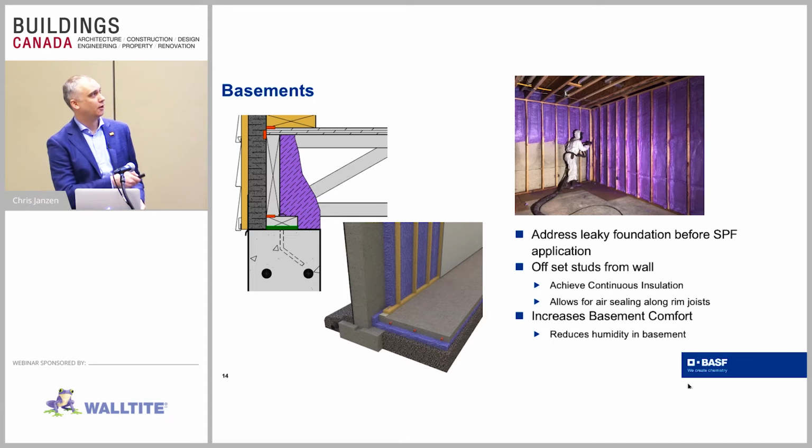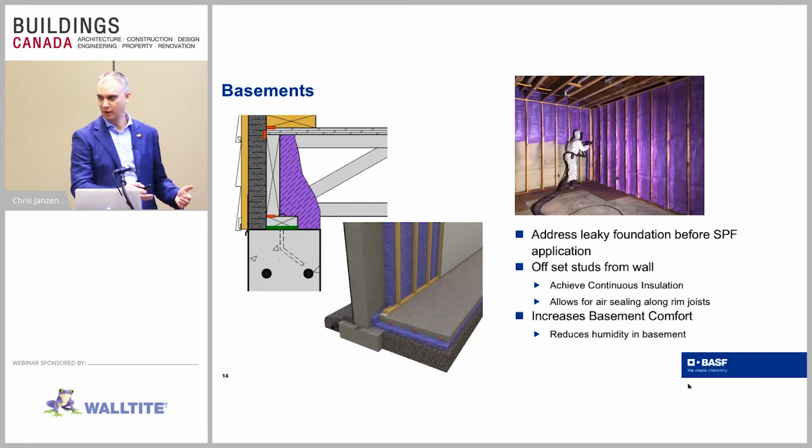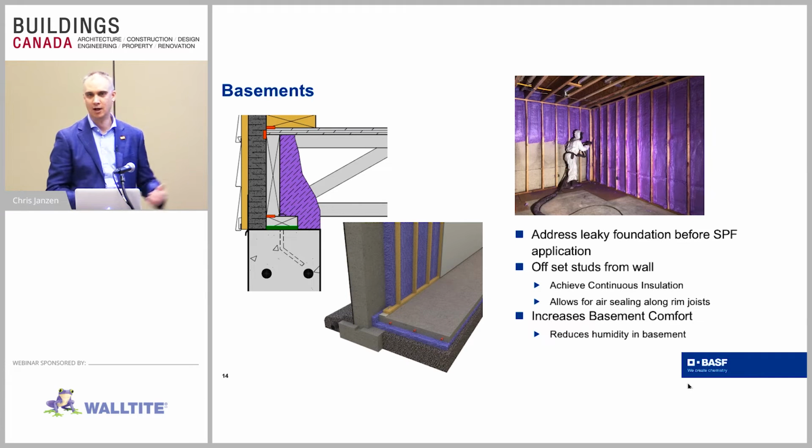One of the key things, though, if you are doing basement renovations and planning to use spray foam, is to make sure that if there are any leaks in that foundation, they're fixed first. Spray foam can go over a leaky foundation. I've seen it done before, where they put spray foam over a crack in the foundation. But if water's coming in there, the spray foam's really just a Band-Aid. It's going to hold the water back, but give it 5 or 10 years and you're going to start having a wet spot on that drywall. So you want to make sure that any leaks in the foundation are addressed properly. Otherwise, you're just putting a Band-Aid over it.